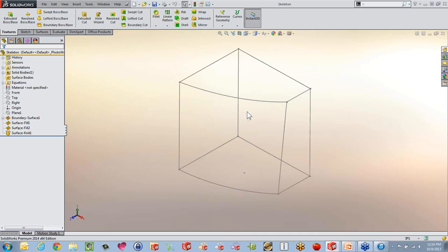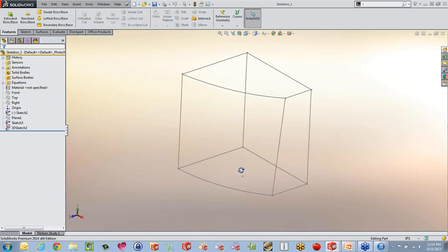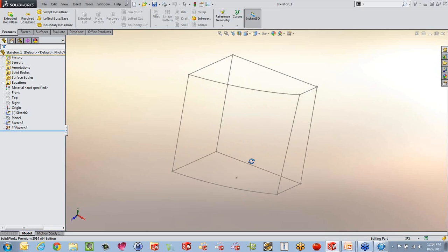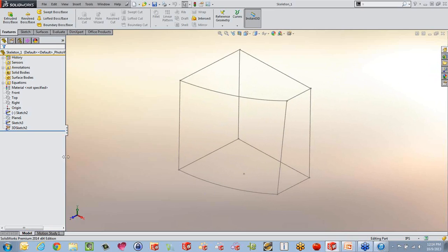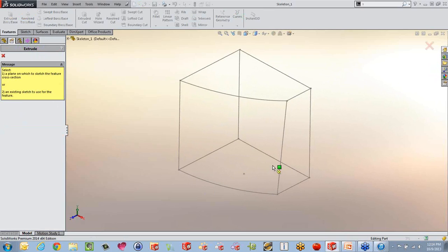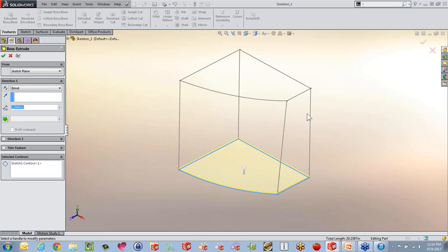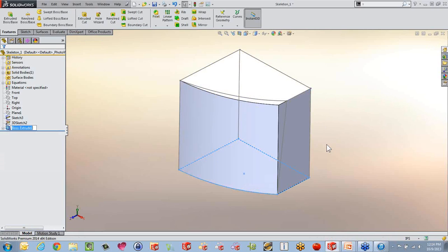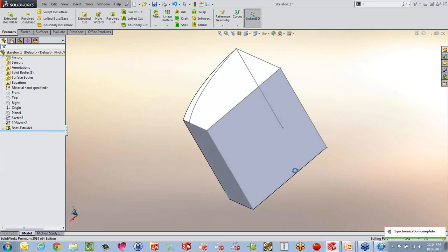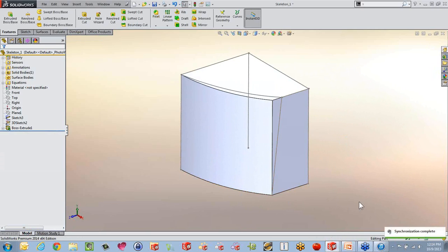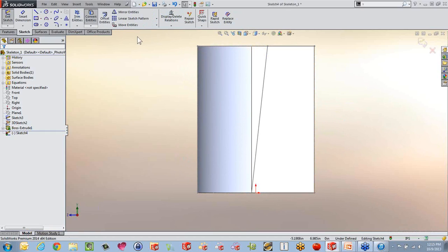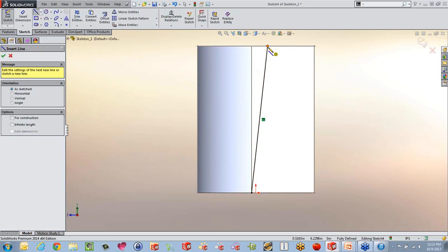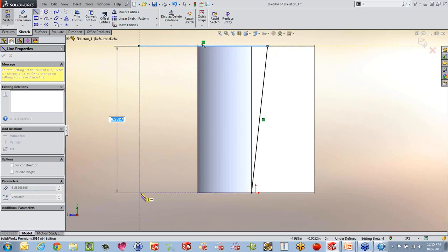If I jump back and look at the skeleton of it, these are the sketches that I built it up from. We could surely do this in SOLIDWORKS with standard commands, right? I could go in here and create a boss extrude, starting from here up till here. So now I've got this rectangle, or this block, that is following the bottom one, and then I would open up a sketch on this face here and do a convert entities to steal this edge, and now I could sketch the remaining and maybe do a swept cut, something like that.